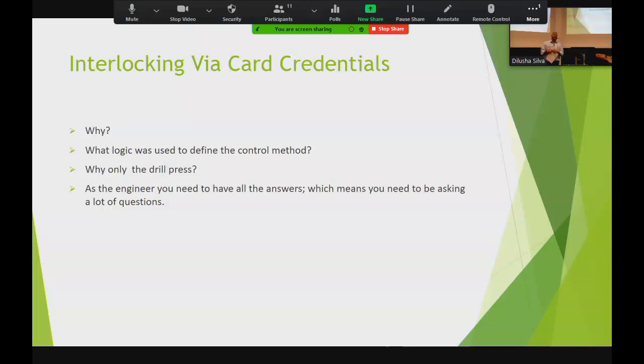Right? You've got a card reader. How are you going to fit it to the machine? I reckon this machine is almost as old as me. So it's old and craggy. If you try and drill into it, it's just going to fall apart. So the next question is, you're going to fix a device to a metal box. Have you thought about earthing and things like that, labelling? So it's just a case of ask the questions, keep prodding at it, find out what the client's end result is.